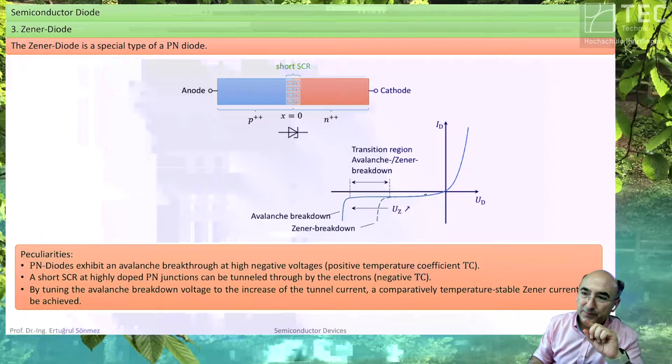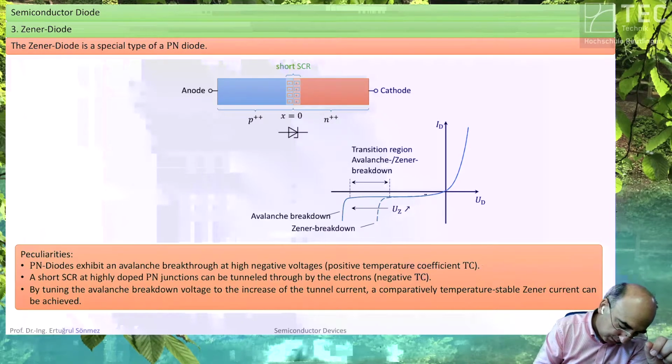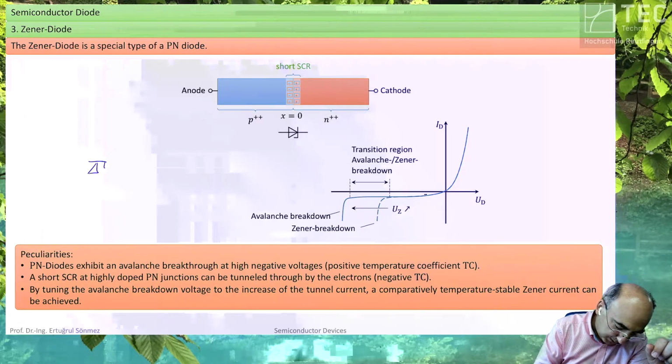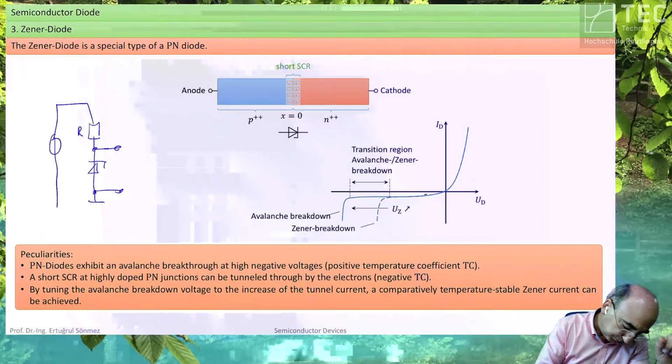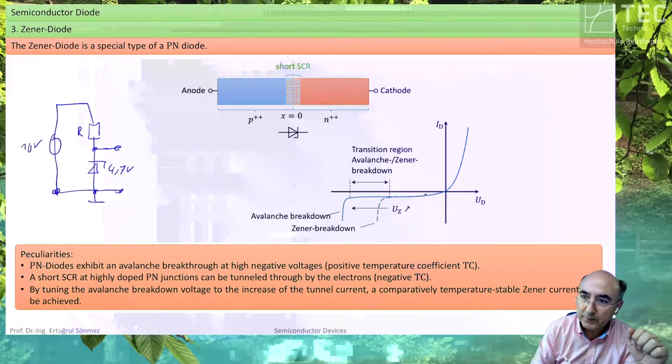And that's the purpose. You generate this with a Zener diode by doing the following thing. You reverse bias a Zener diode towards ground. You add an additional resistor to a voltage source. Let's say that's 10 volt. Your Zener voltage is 4.7 volt, let's say.